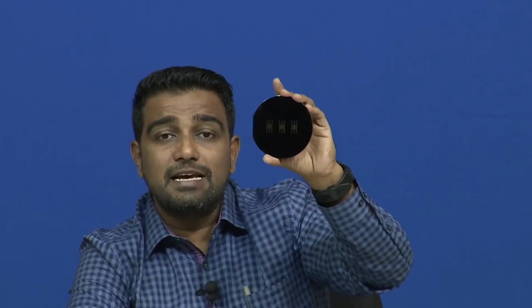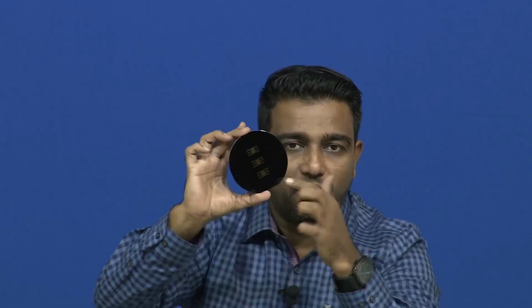Now you can see here there is a rough surface and there is a polished surface. When you talk about wafers, they are polished wafers or unpolished wafers. If one side is polished, it is called a single side polished wafer. If the polishing is done on both sides, it is called a double side polished wafer. Depending on the diameter of the wafer, the thickness varies. For this 4-inch wafer that I am holding, the thickness is about 500 plus or minus 50 microns, that is what is written in the specification. So, this is the 4-inch wafer.